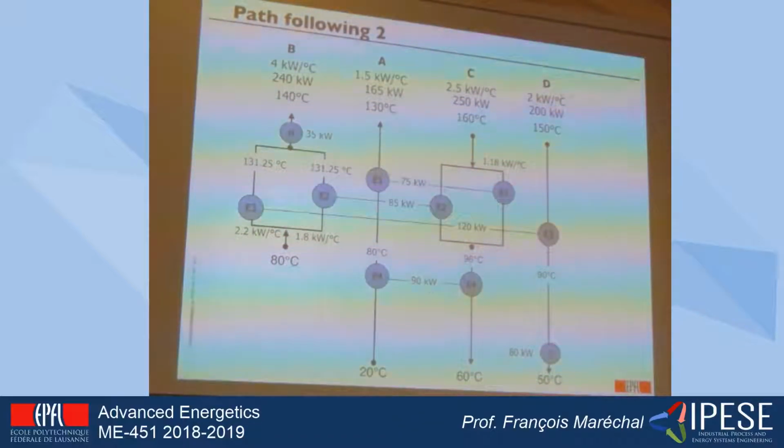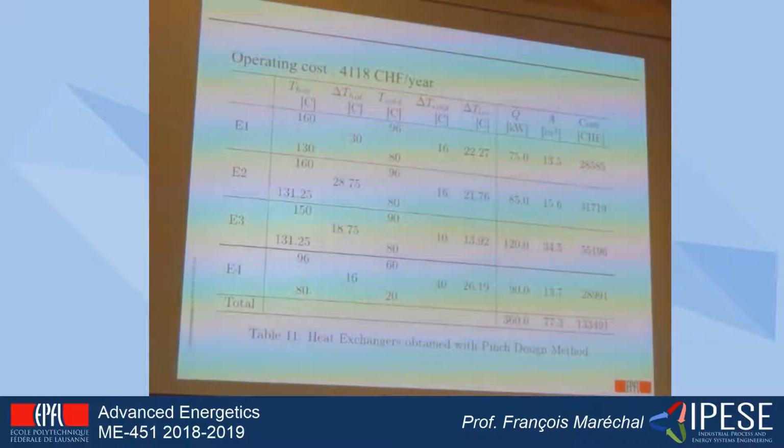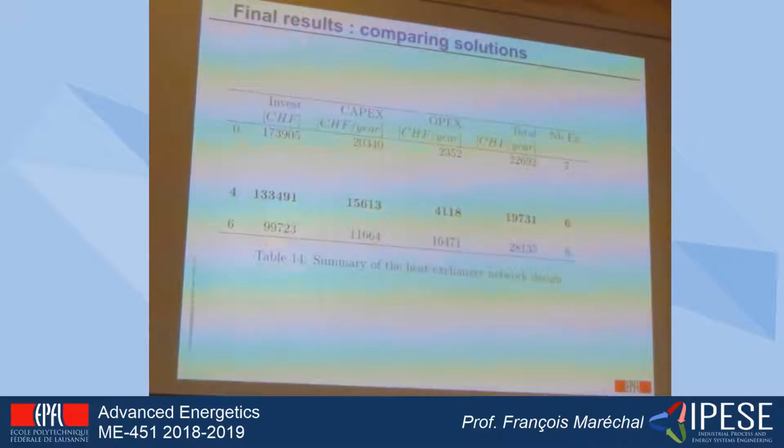But this time, the investment reduction is a little bit less, okay? But the penalty is much lower, which means that when I add this in the list, I will see that I can have something which is cheaper in total cost than the original solution because it has a lower number of heat exchangers, and because I have removed the small one that you were talking about.